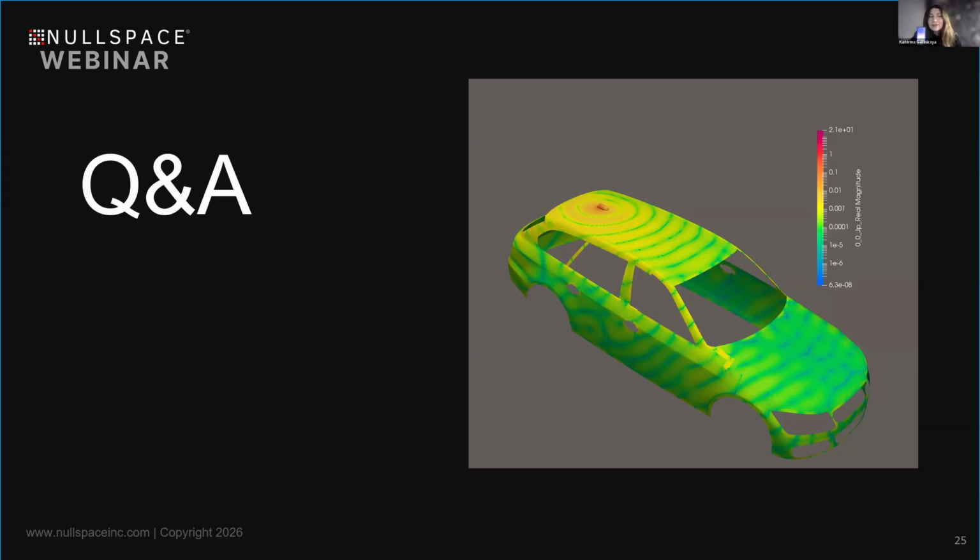So yes, you see here on this current plot that the car is a part of the antenna, but it does not act as a radiator itself. Because if you remember our S-parameter results, we have the standalone antenna with dual resonance, and we have the same resonances still in place with the metal roof and with the glass roof. They are maybe just shifted a bit, with different matching, but the antenna works with the same resonance as it did when it was a standalone antenna.